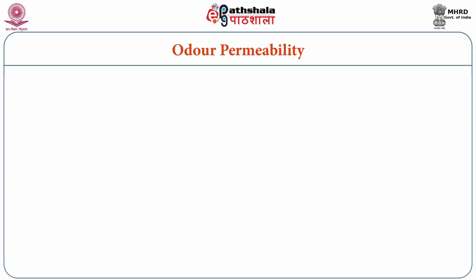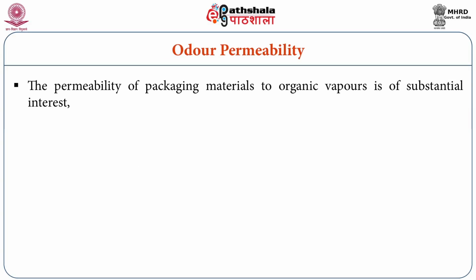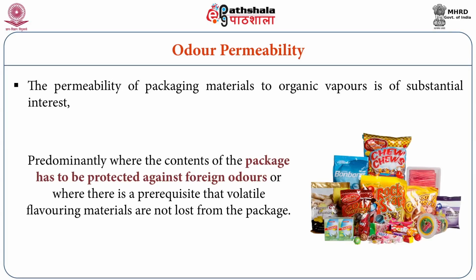Odor permeability. The permeability of packaging material to organic vapors is of substantial interest, predominantly where the contents of the package have to be protected against foreign odors or where there is a prerequisite that volatile flavoring materials are not lost from the package.